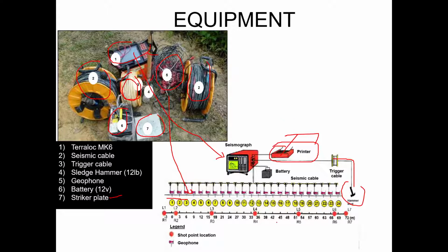We have a few spots to get this seismic data, normally about 7, sometimes 5, sometimes we can do 9. It depends, but normally they use 7 shot points. If you increase the number of shot points, you can get better data, but it takes longer to do this testing. This is what we call a shot point. Now we can show you what the shot point means.